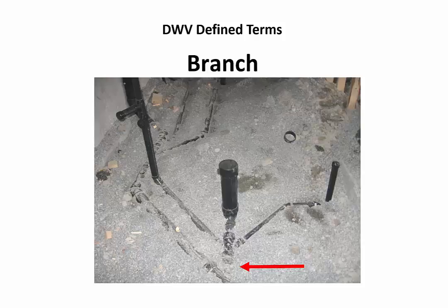This picture shows an underslab drainage rough-in. The water closet and bathtub are both wet vented symmetrically through the adjacent lavatory fixture drain. All 3 fixtures drain through a 3-inch branch as shown.